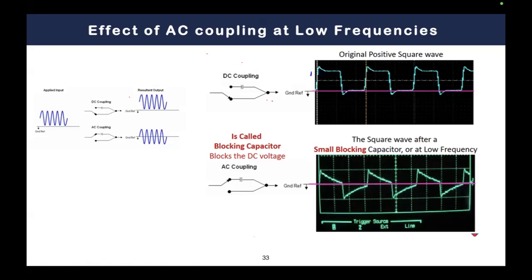You cannot now consider the capacitor as a short circuit in the AC, because simply omega is small, with still a capacitance in the microfarad range, for example. So it's 10 to the power negative 6 times 10 to the power 2. If we assume that this is a 100 hertz square wave, this leads to 1 over 10 to the power negative 4, which is 10K equivalent impedance. And here you have a capacitive effect that's easily observed. This also leads to what we can call a filtering effect.